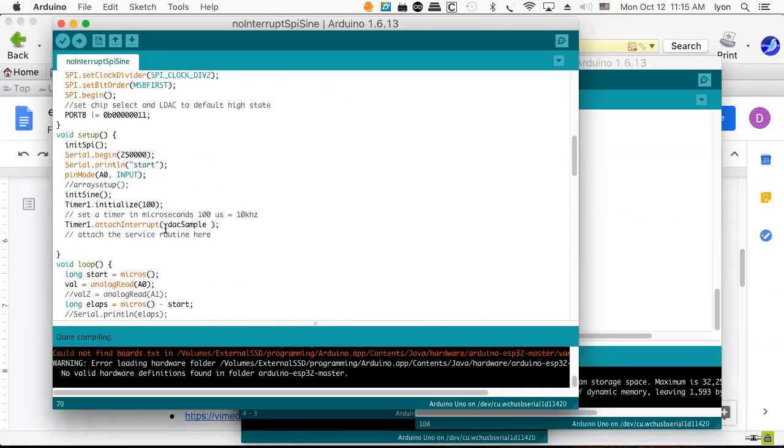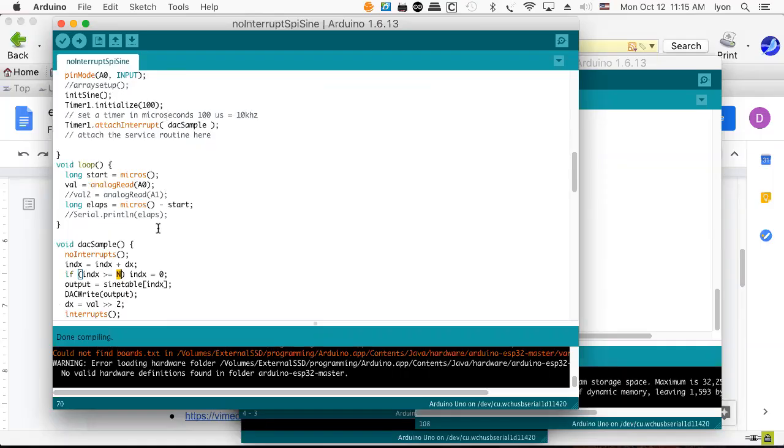So if you wanted that to go to 4,095, 4,096, then take 4,096 divided by 128 and get a number like 32. So if you wanted the output to be equal to index times 32, then you wouldn't need the sine table.